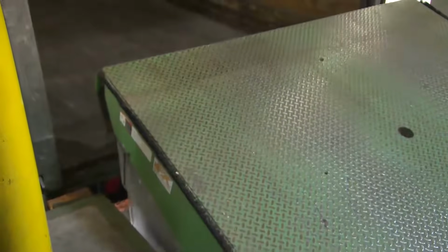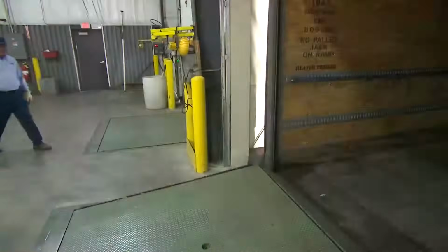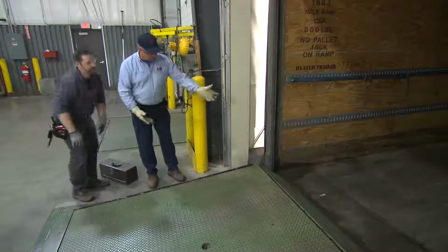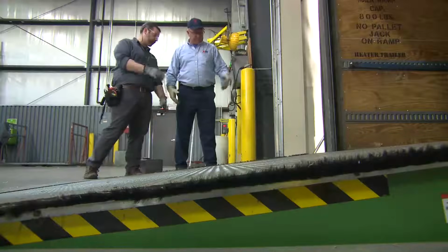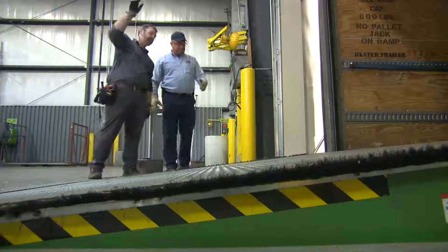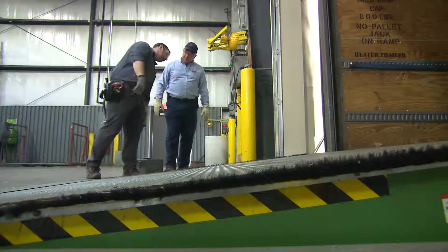Make sure portable dock boards overlap both the dock and the trailer by a safe distance. A best practice is at least 8 inches. Inspect dock boards regularly and as necessary for cracks, bends, and any other signs of failure. If you spot any defect, they'll have to be repaired before that dock board is used again. A qualified person needs to be involved with any repairs involving a dock board's structural integrity. Remove it from service if repairs cannot be done. You don't want anyone else using a defective dock board, right?